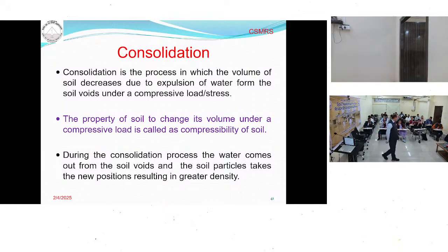Have you seen a sponge? Suppose a sponge is filled with water and you compress it. What will happen? The water will come out. The same thing is happening in soil. When the soil is subjected to a compressive load and it is saturated, the water will come out from the soil, and the soil will compress or settle.